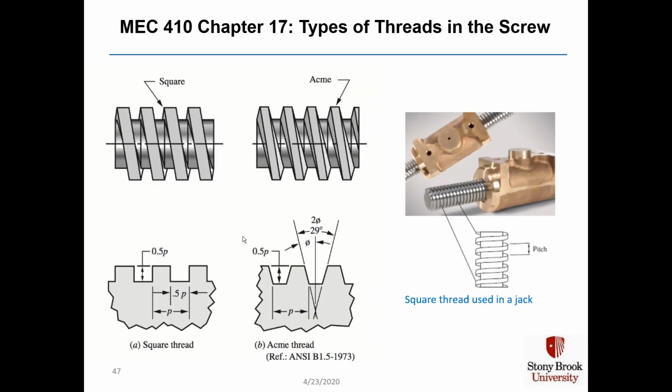Here's a type of threads that are in these scissor jacks and in these jack screws. Normally it is a square thread, which is what we're going to analyze, and it gets its name from the fact not that the view of the threads itself is square, but if you make a cross section which goes right down the central axis of the screw, in the cross-sectional view the thread has the look of a square opening and then square metal, square opening, square metal.